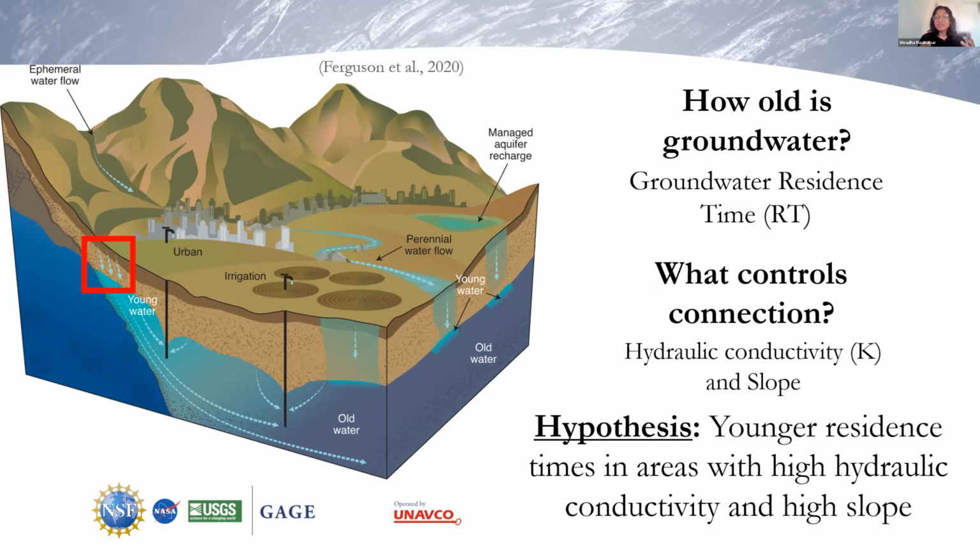For example, if you have really small grains of soil, like silt, you're going to have less space between those rock grains, and so that makes it difficult for water to flow through. But if you have really large rock grains like gravel, there's lots of space for water to move between, and you get a higher hydraulic conductivity. With the smaller rock grains, you've had a lower hydraulic conductivity because it's harder for water to flow through.